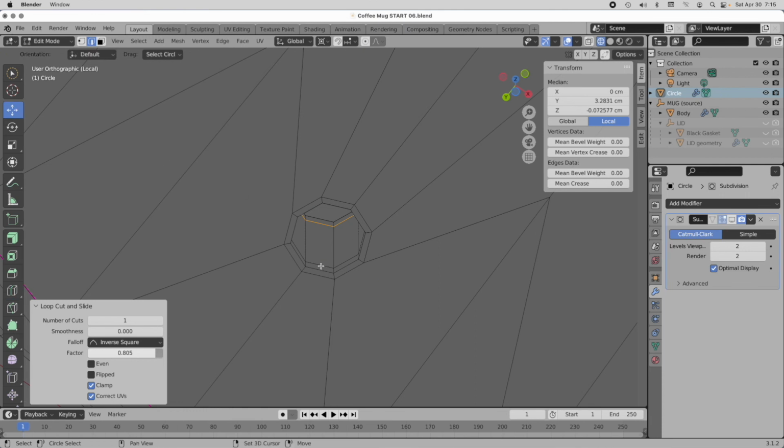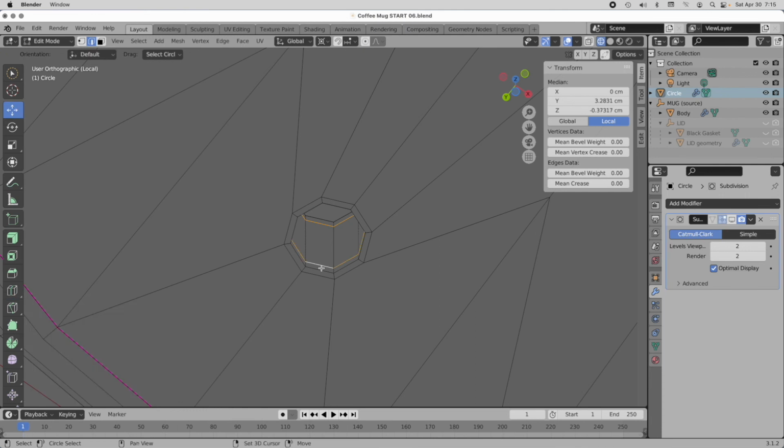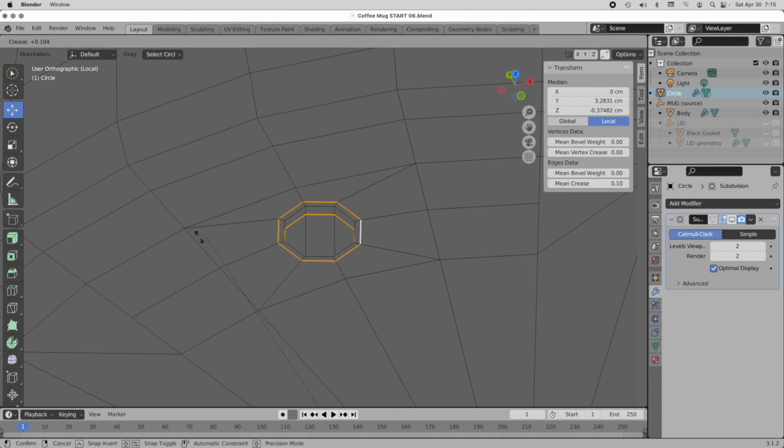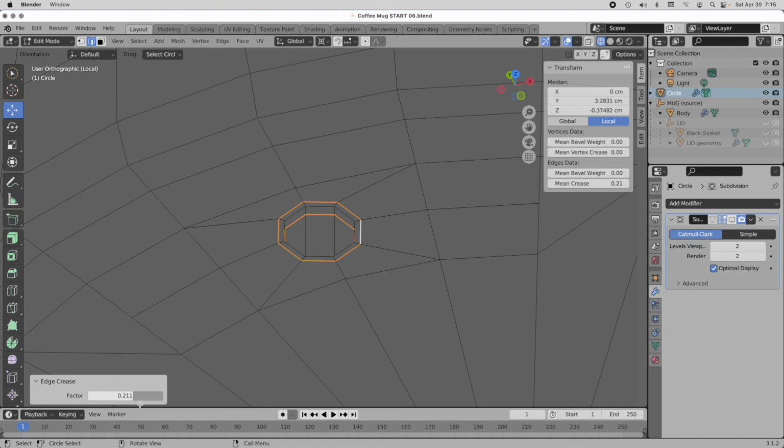And then finally, I'm going to hold the shift key, select those and those, come to the top, hold the shift key again to add these to the selection, and then press shift and E to assign that hard loop. Now you see here I didn't get all the way to 1. I got impatient, so now I just type in 1, and that will add that in.